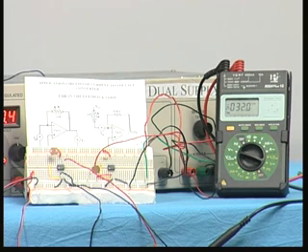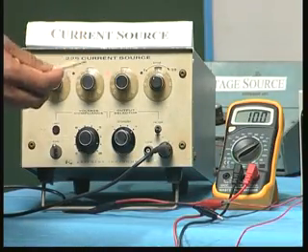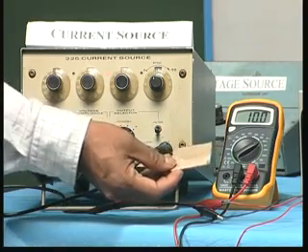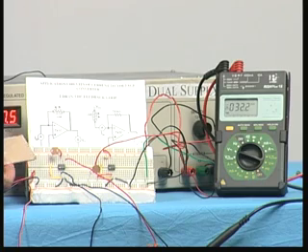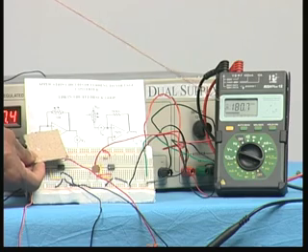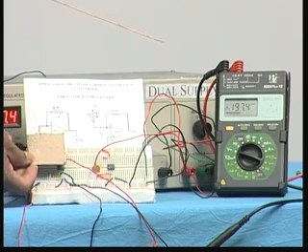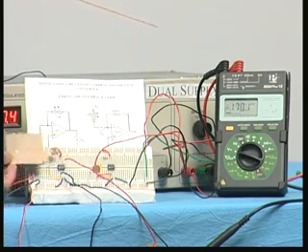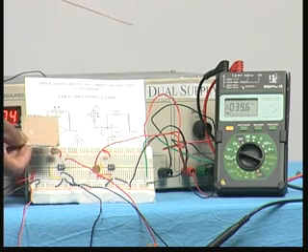Now if I close the LDR using a small cardboard, you know the resistance will increase, and therefore the current to voltage converter output also will increase, because R increases, I into R should also increase. Now keep observing the multimeter reading as I bring the cardboard and hide the LDR. Now I have closed the LDR, you can see the voltage is somewhere around 180 or so. So when I remove it, again it comes to around 30 or something. So when I close it completely, you find it can go to very high values, 200, 300 millivolts and things like that.